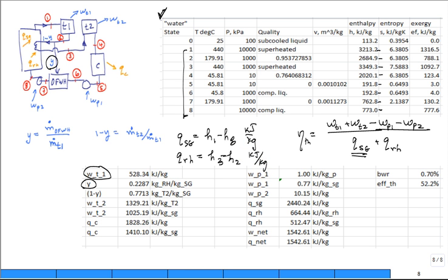If I have 1 kilogram flowing through or into the first turbine stage, how many kilograms do I have flowing into the reheat section, or do I have less? Do I have 1 kilogram or less? You have less. And so what we do is put everything on the same per kilogram scale.